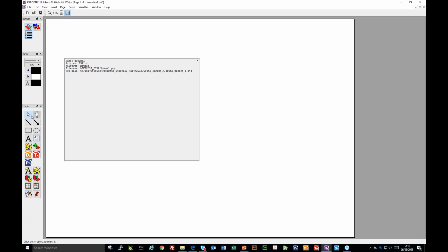Or I could use the Select tool and copy and paste to create a copy of that D3 plot object. And then we could update the capture on that second object to change the data component to X displacements.